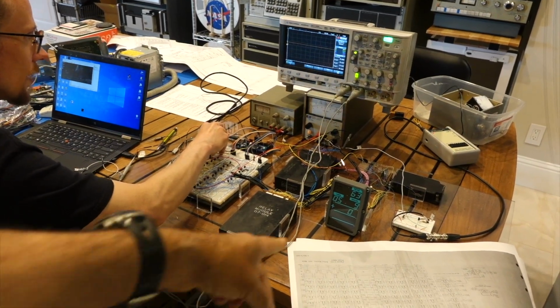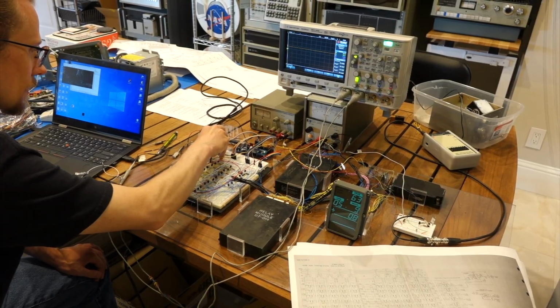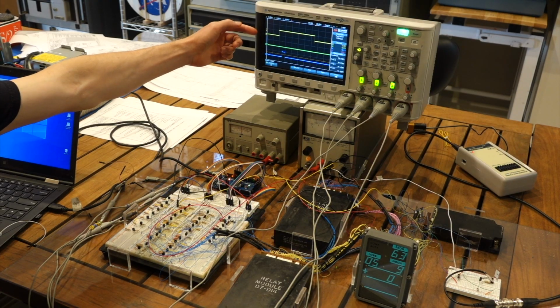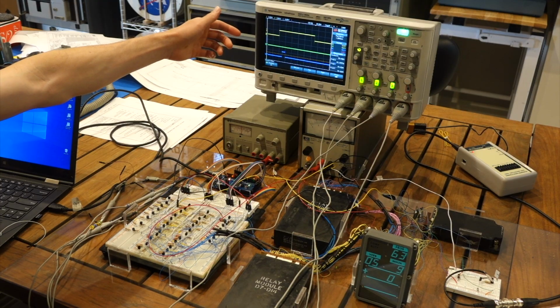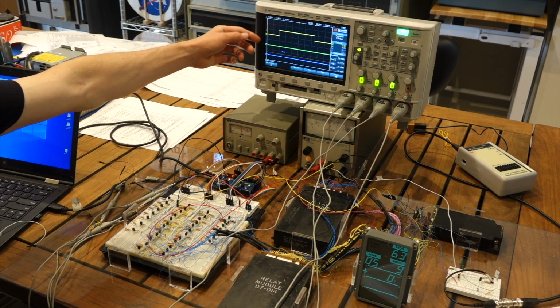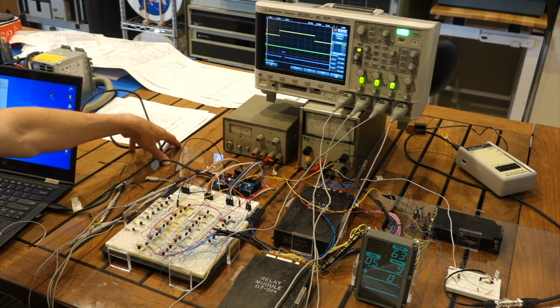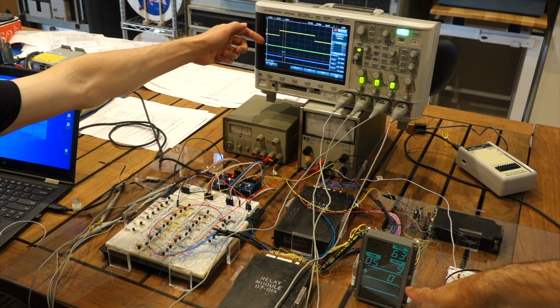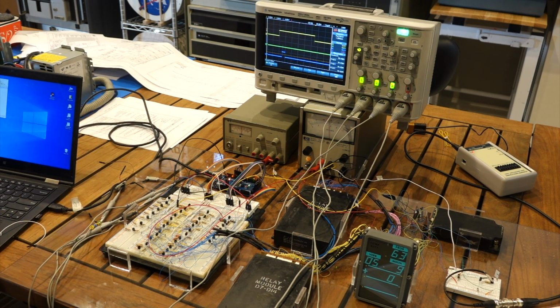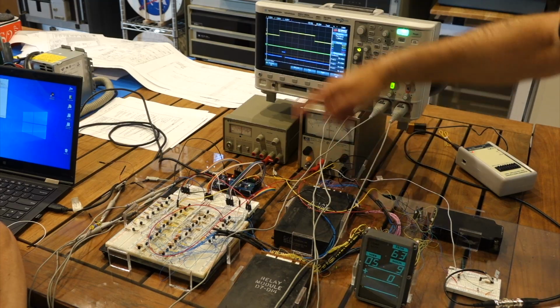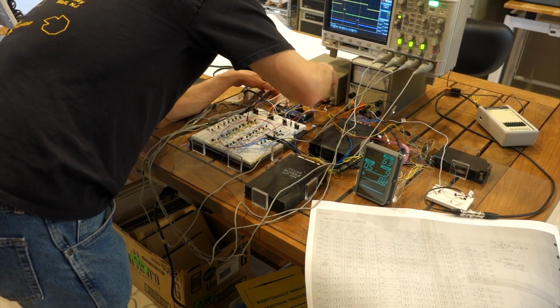So we couldn't see anything, so I changed my toggling software to a digit that works. Right here at the top is the row drive signal, and this essentially goes high to select the digit that you're trying to access. Exactly. And then the 2 signals below here go out to the same physical relay, and the top one goes out to the set coil, and the bottom one goes to the reset coil. And so when we flash this digit on and off, first we hit the set pulse, the set coil, and then the reset. Set. Reset. Okay, so what we think is that since the whole second digit is not working, that line is broken somewhere.